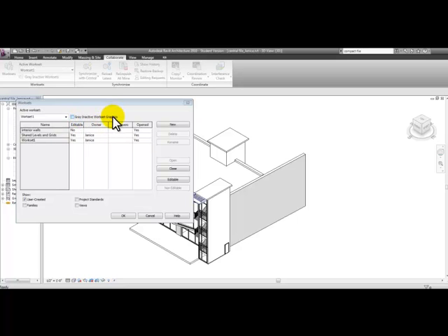If a workset is open, it is visible, but if it's not open, then it won't be visible. This is the perfect way to turn on and off the different worksets. Everyone on the team needs to be aware of the rules of working with worksets to coordinate changes within the project.